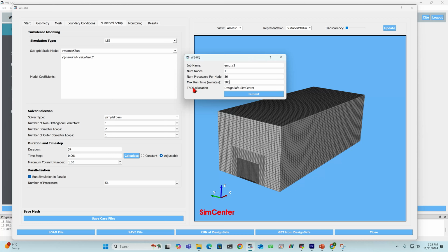And then the next thing that you need to be cautious about is the maximum runtime. In this case, I have already run the simulation previously, and I know how long it's going to take to finish the simulation. Basically, this process is trial and error, but for now, we're going to use whatever duration I have used before, which is approximately 4-point-something hours.